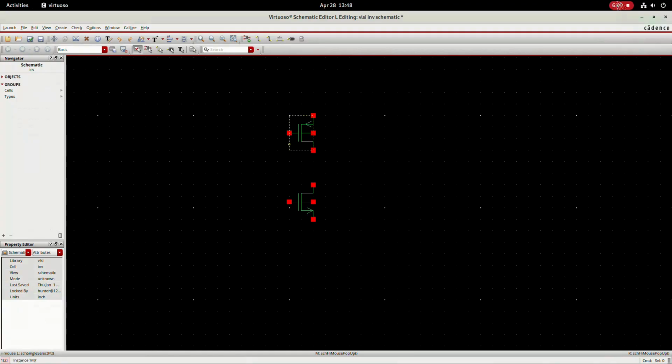You see here is Create Narrow Wire. Near this there is Create Wide Wire. You see this is a narrow wire, and this is a wide wire. See, the wide wire is much bigger than the narrow wire. In this full tutorial we are going to use only the narrow wire. The wide wire is only for bus control. If you are designing an 8-bit counter or some protocols with 8-bit or 4-bit, you can use this. We can split this single wire into as many bits as we need. So now we don't want it.